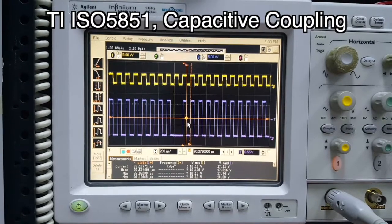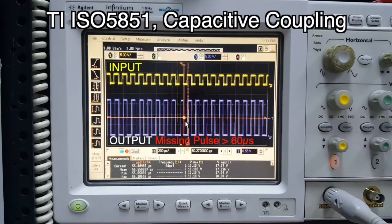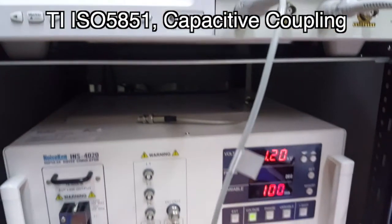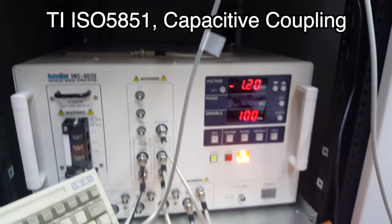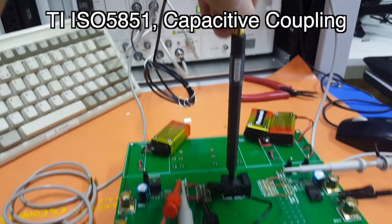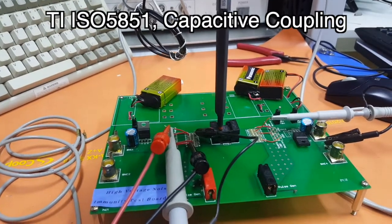Next, we're going to test Texas Instruments ISO5851, which uses a capacitive silicon dioxide isolation core to couple signal across the isolation barrier. The power stage consists of DSAT detection circuitry to monitor the IGBT collector-emitter overvoltage. The TI gate driver has missing output pulses when negative 1200 volts periodic impulse noise is introduced on the surface of the gate driver's package.